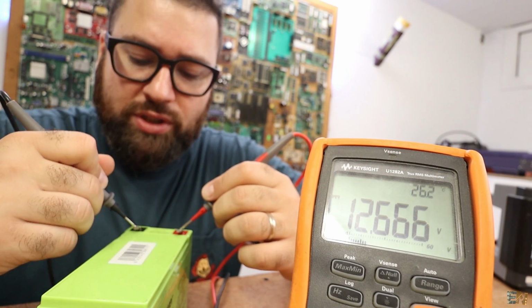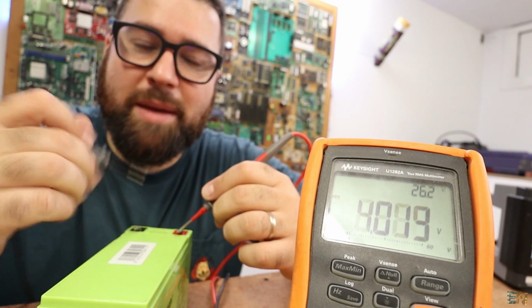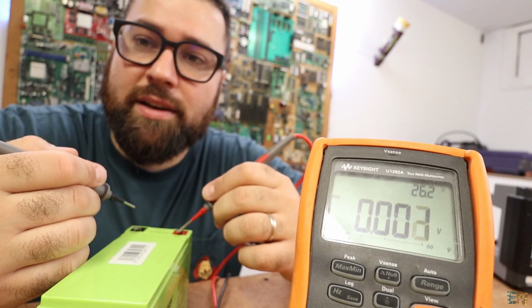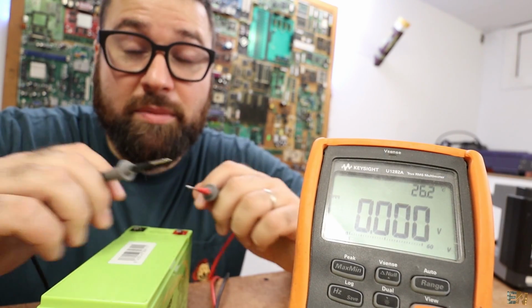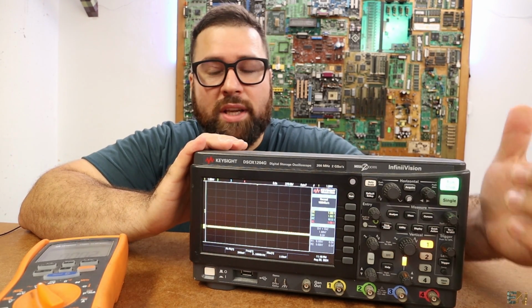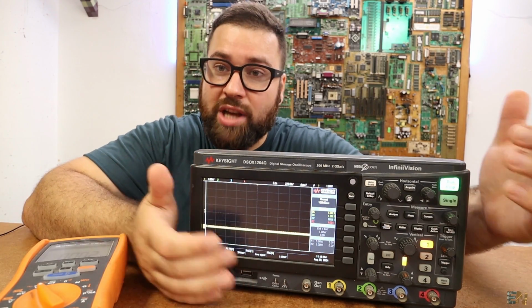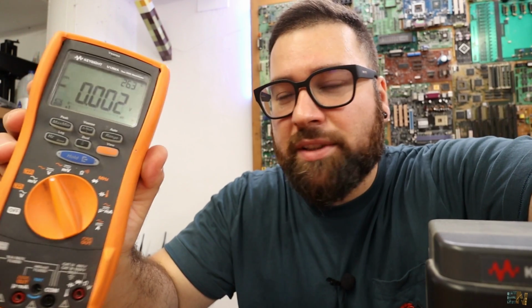But what if I change the voltage like this, very fast? As you can see on the screen, I'm getting random numbers, so we can't understand anything that happened here. If I want to see those changes in voltage, I need another variable. Now, an oscilloscope also measures the voltage, but this one uses another variable. It also takes into consideration the time. So you can see the voltage, how it's changing over time. And that's very important.